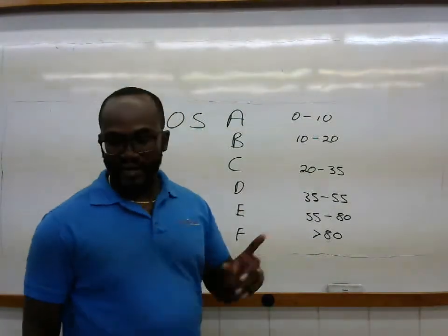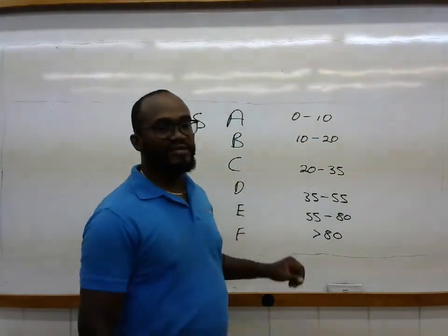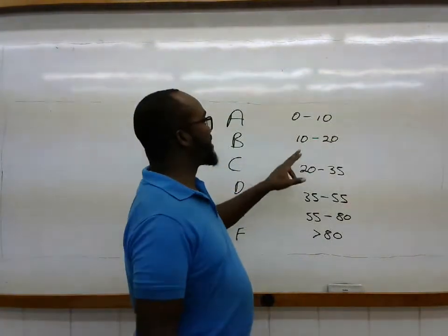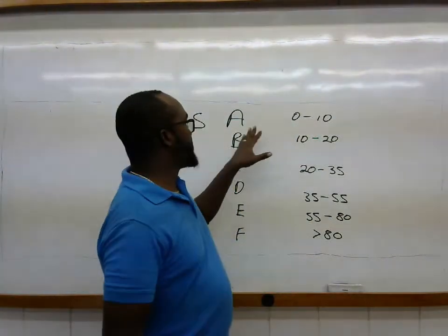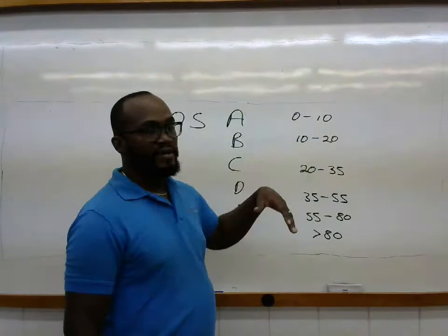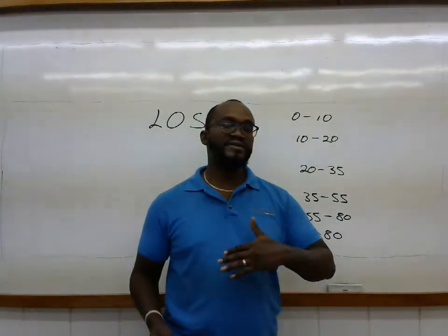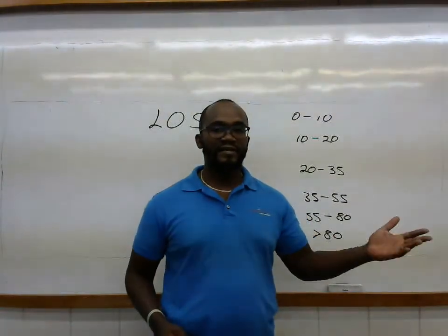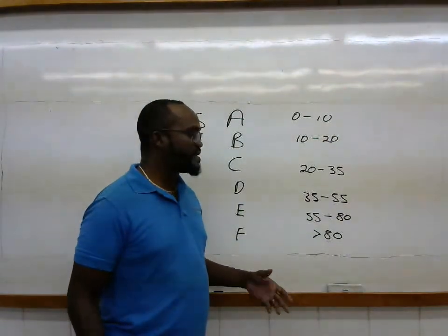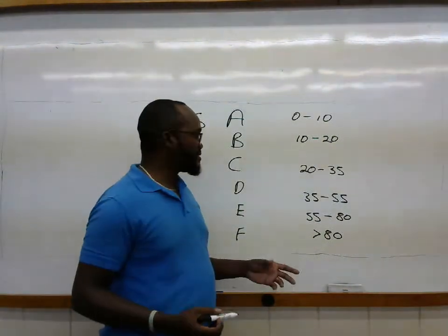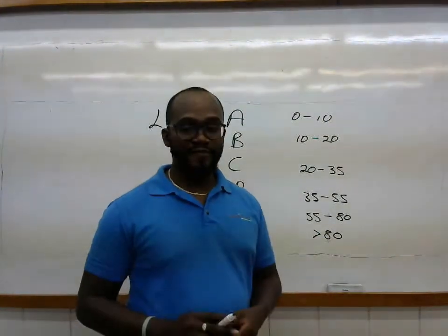What does this mean? Well, I'll go through the definition of delay shortly, but essentially, it's delay associated with the traffic signal. So, for example, once you're delayed less than 10 seconds as a result of the traffic signal, you will be experiencing level of service A. In practical terms, level of service A would be as if you had no congestion at all and you were able to proceed through the intersection fairly easily. Level of service F, being the other extreme, would be what we call jam density conditions, or where we have chronic congestion essentially and you're in gridlock, so you cannot move.